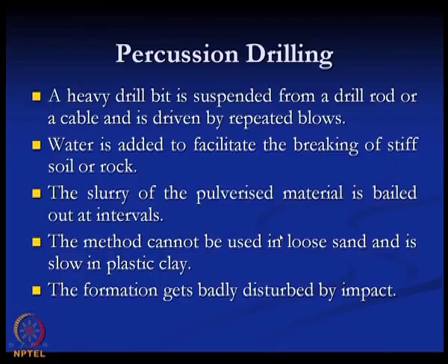So, when you are talking about this type of boring, and all the borings except the auger borings, a drill rod is there and a bit is attached in front of the drill rod, and this drill rod is pushed into the soil and it is driven also. Then this drill bit helps to advance the rod into the soil or borehole, and whenever a soil sample is required, this drill bit is replaced by the sampler.